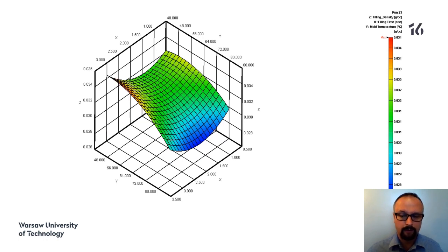Okay, here we have the same mold filling imbalance, but right now, instead of melt temperature, we have mold temperature, and we can see that it is always better to use higher mold temperatures to reduce the mold filling imbalance. And like in the previous case, we cannot inject too slow. We need to find an optimal value of our injection rate.